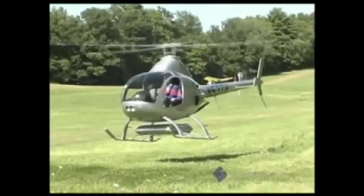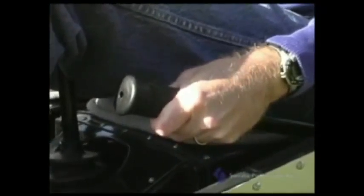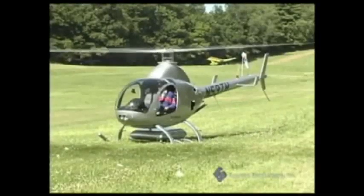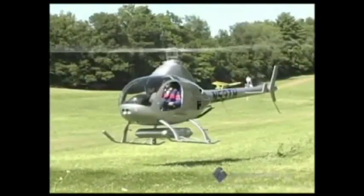When the collective is pulled up, what else must be done to maintain the proper RPM of the blades? When total rotor thrust is increased by lifting the collective, more power is required to maintain a constant RPM, which in turn requires an increase in throttle. As the total rotor thrust increases, we increase lift until it is greater than the weight of the helicopter and it starts moving up. The opposite is also true.